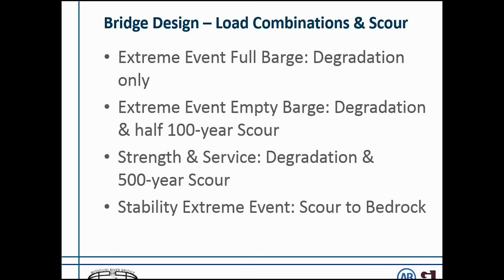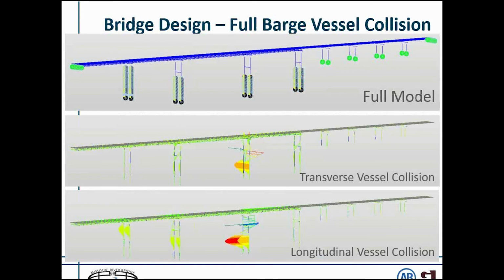And then we had to do a stability check that is an extreme event case, and that is considering scour to bedrock. For our river piers, the extreme event full barge load combination cases controlled our design. So that's what I'll continue to talk about.